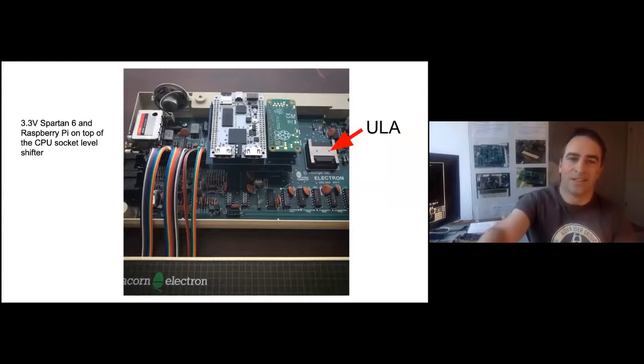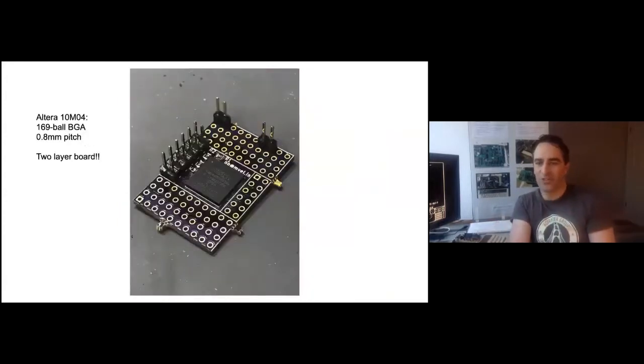So time went by. I happened to decide I wanted to experiment with BGA chips. Basically all the interesting looking chips seem to be in BGA. A horrible format for hobbyists, but I figured if I could get it working, it would open up a lot of possibilities. Also, 4-layer boards are really expensive to make, so I tried to get it to work on a 2-layer board.